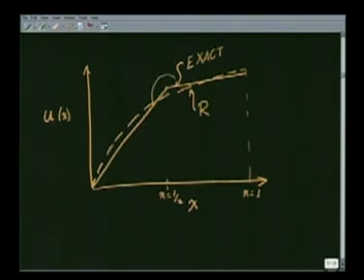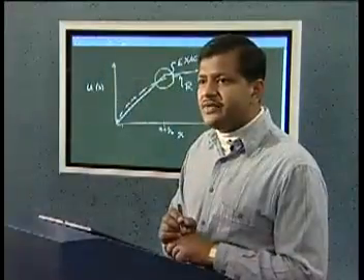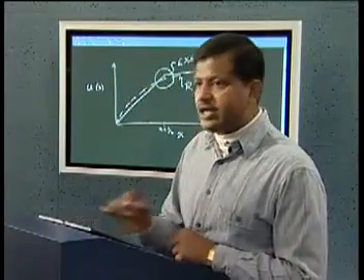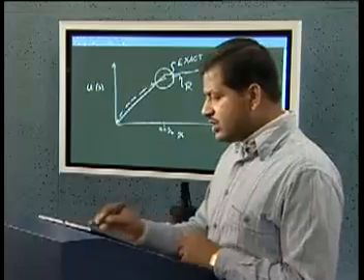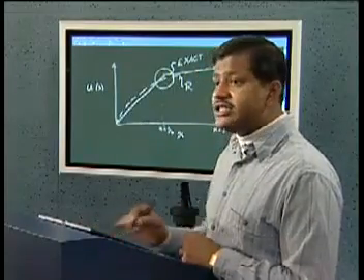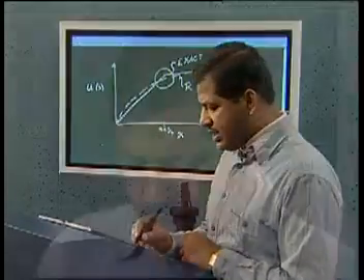So at this point x equal to half, you will not be able to capture the change in the slope using the Rayleigh-Ritz solution. Whatever you do, your function may come close in terms of the values at the points, but the derivatives will be completely off at the point x equal to half, because this function is going to get a change in slope at the point x equal to half.